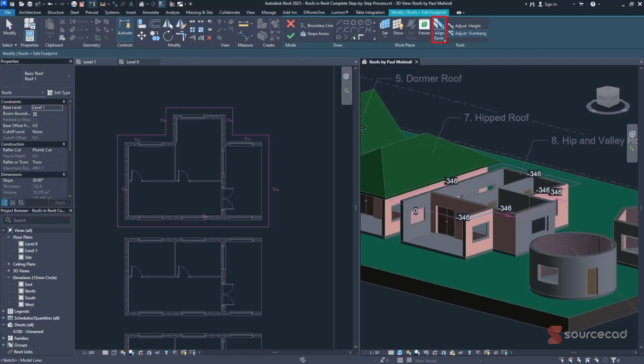So in the event that you have your eaves at different distances from the specific wall, you're going to have these distances shown here. If you just want to adjust, let's say, the height, you can adjust the height, or the distance at the terminal, or the overhang total distance. So it depends on what you want. It's quite simple. Let's say we go with height.